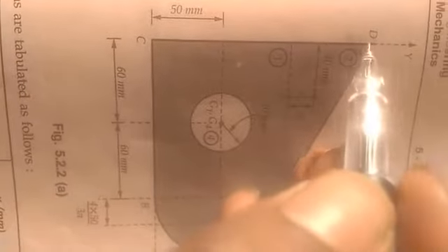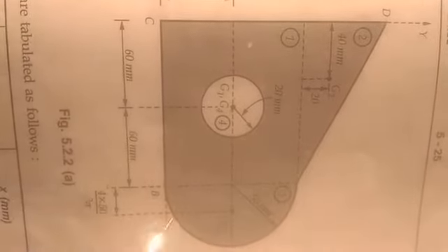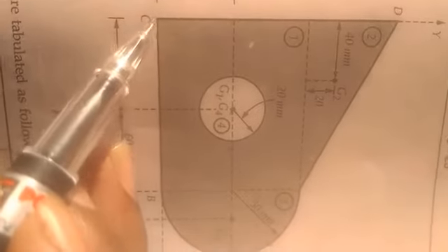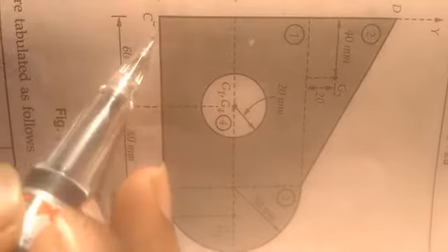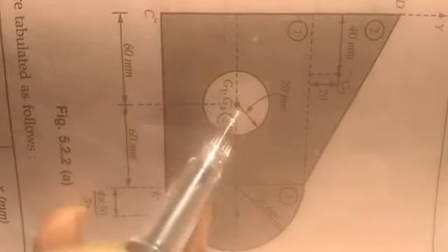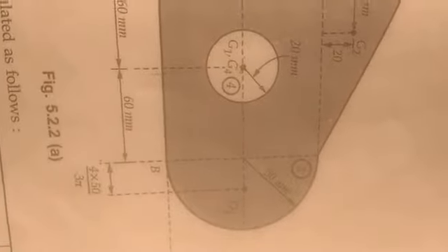So if you take this one as the y-axis and this one as the x-axis, in the beginning, whatever section they give, in the left extreme corner you make the x-axis and y-axis, with this point as origin. Okay. So from here to here 60 mm, and from here to here it is 50 mm. So (60, 50) will be the CG of the rectangular section. Okay. The same thing applies to the circular section also. See, this is the fourth section. I will come to this later.